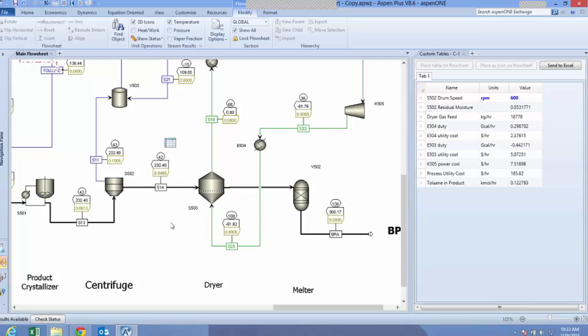You can imagine how this can make a flowsheet much easier to understand. Maybe if I was looking at an electrolyte flowsheet, I would have put pH there. If it was polymers, I would put on maybe the intrinsic viscosity or the number average molecular weight. So this can make the model really talk the language of the process and make it easier to understand.